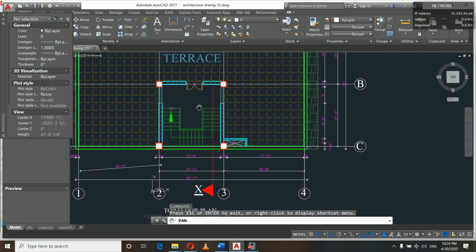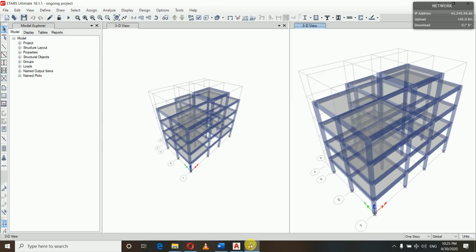So this is the slab portion, and the reference points for this slab are here, one point is here, here is another point, and one point is here. And to start our staircase, we have the reference points, first point is here and second point is here, and from here our staircase will run, and then again there will be the reference points here, here, and here also to give the landing slab. So let's start how to do it. First we will make our reference plane.